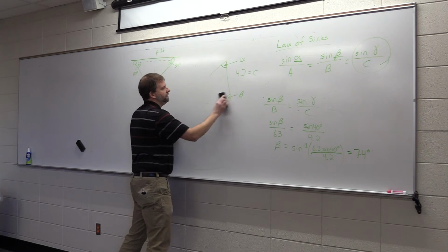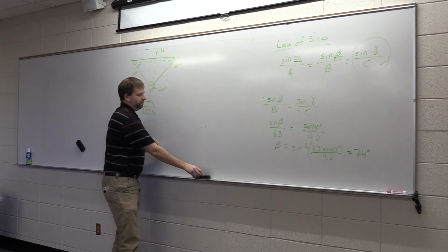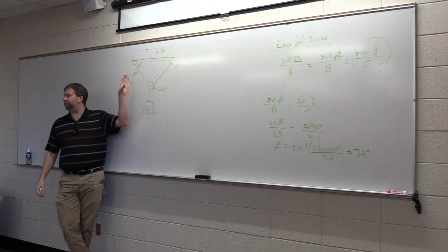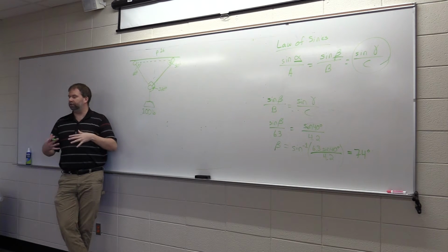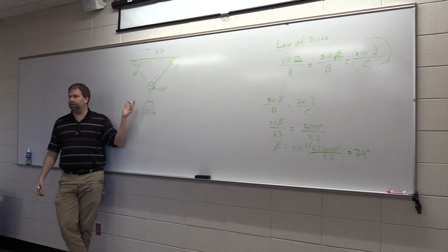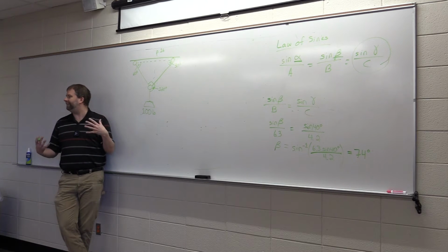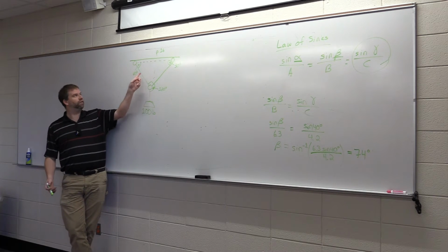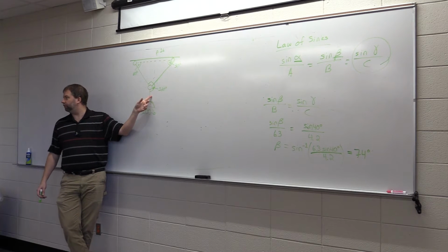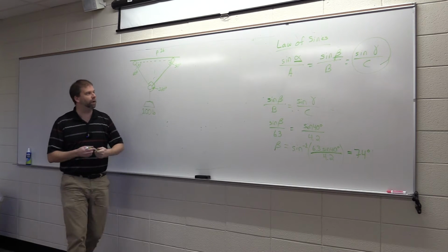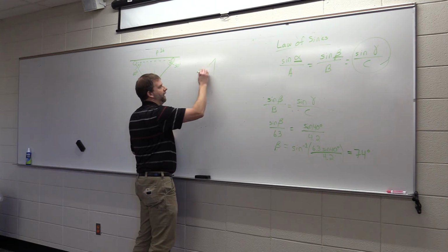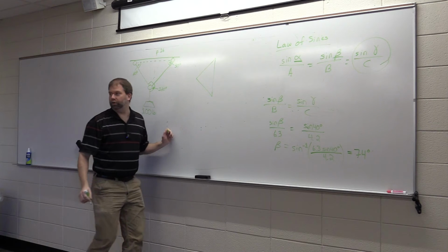The idea behind the force polygon is that if you have a system of forces that are all in static equilibrium, it doesn't matter how many forces there are, 3, 5, 7, 1,019, if they're in equilibrium, you will be able to draw a polygon with that many sides that will close. In this instance, we have 3 components carrying force. So if this thing is in static equilibrium, we should be able to draw it in such a way that we have a closed polygon.